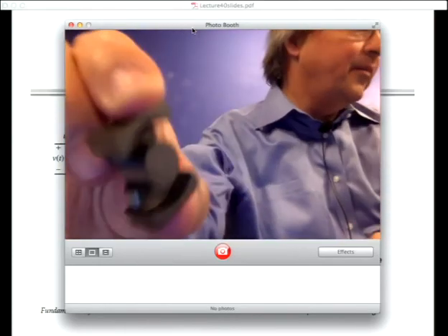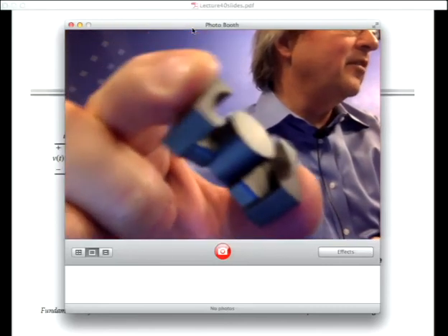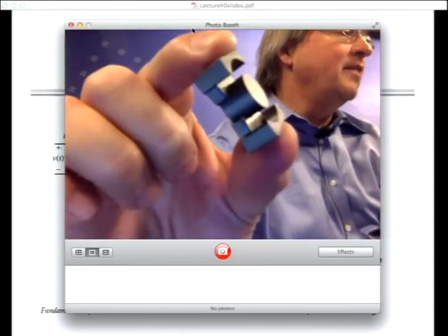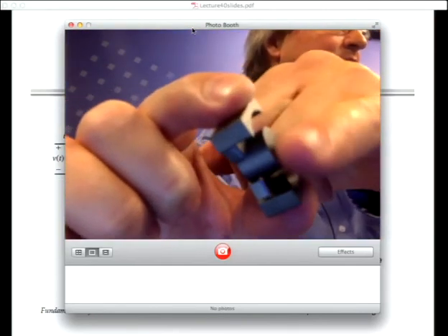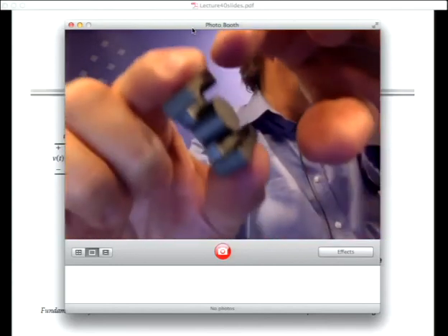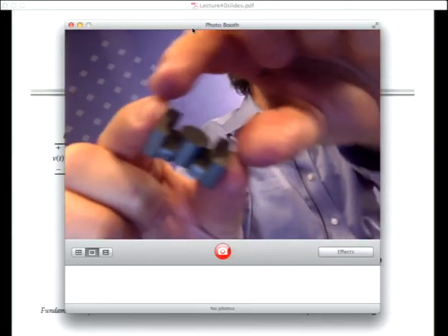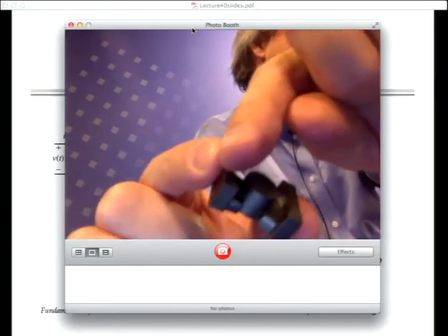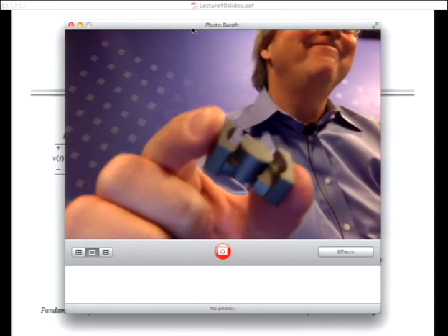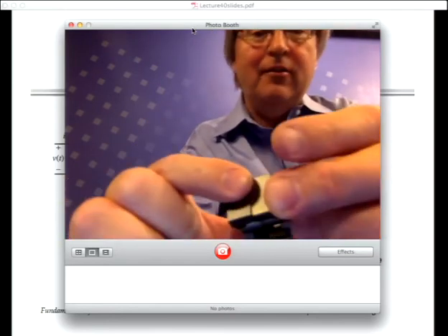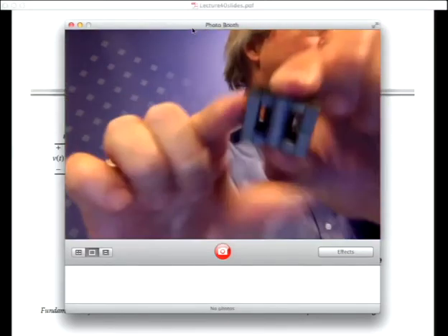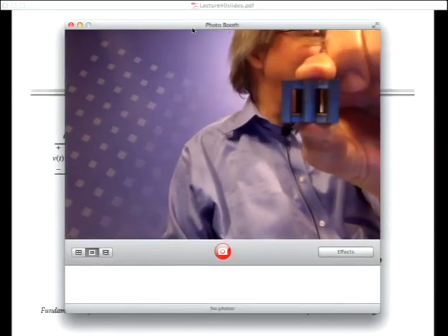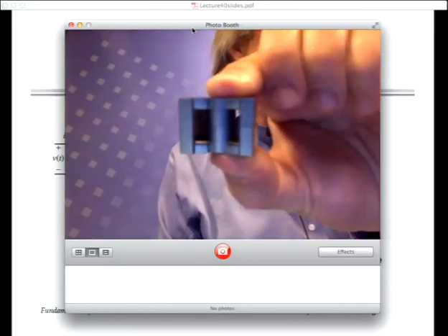So here's what the ferrite core actually looks like. These numbers on the core are generally related to the dimensions in millimeters. This distance from here to here is 26 millimeters. And then when you stack the two core halves together to get one complete core, the height is 20 millimeters. So the bigger the number, the bigger the core is for real.